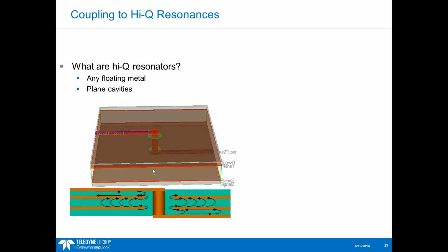So we have the signal propagating along, and there's a ground plane right underneath it. So all the signal return current is flowing in that ground plane. But when it gets to the via, as the signal travels down the via, there's no obvious signal return path, and it takes some complicated route, and the energy ends up coupling out into the cavity.